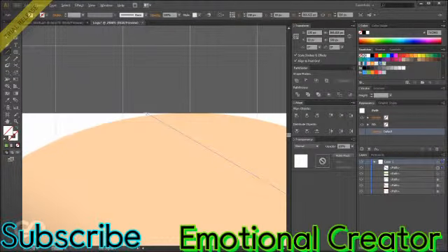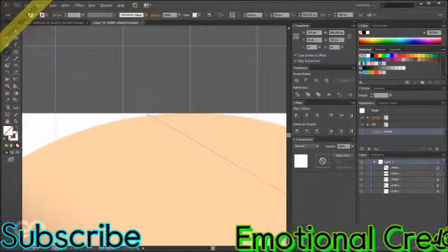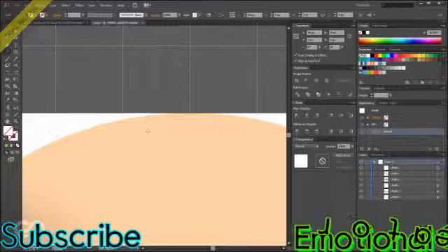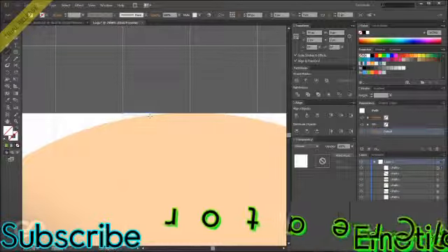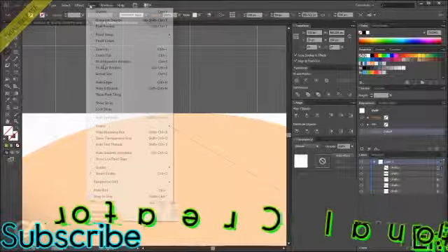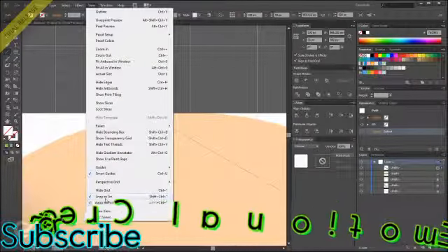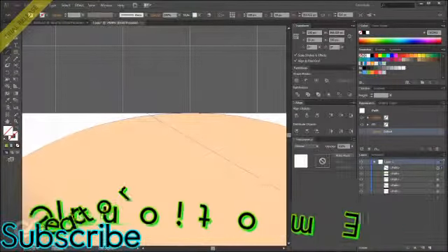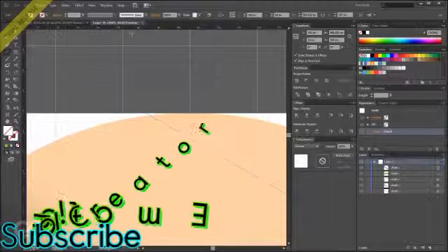Now I want to start another line which is exactly starting here, but if I click, you can see that it creates a line which is going somewhere halfway. The reason for this is because grid snapping is on. I'm going to turn off grid snapping, and I'm also going to create a grid line.